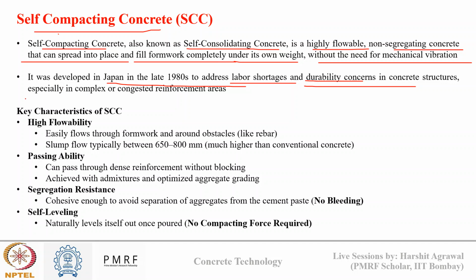Okay, especially in case of congested reinforcement area where concrete flow may not be proper. So what are the key characteristics of self-compacting concrete that makes it so special? It has high flowability, where it can easily flow through formwork and around obstacles like rebar.